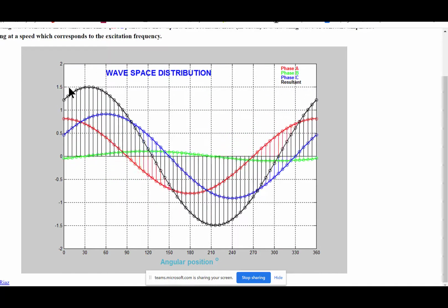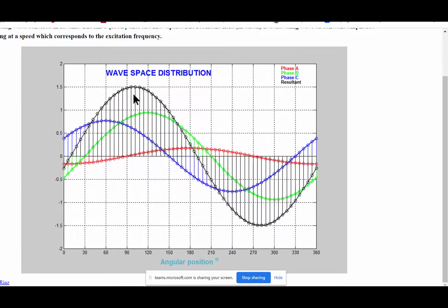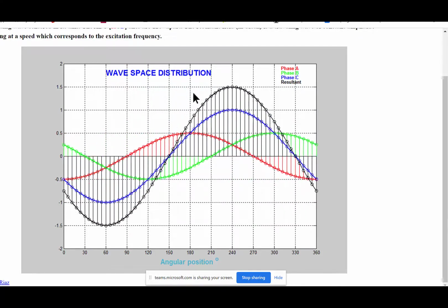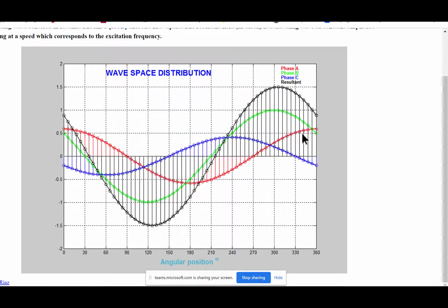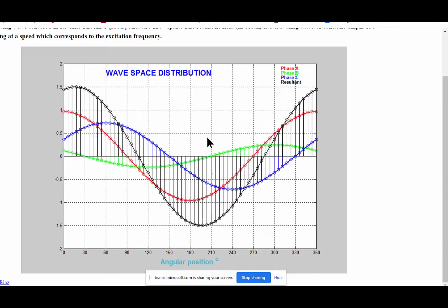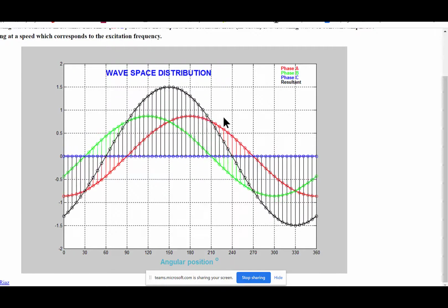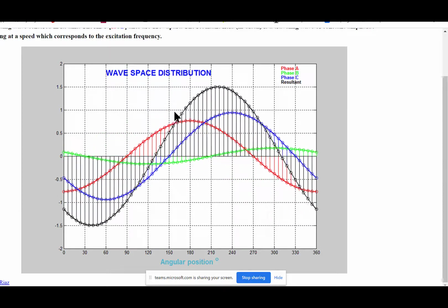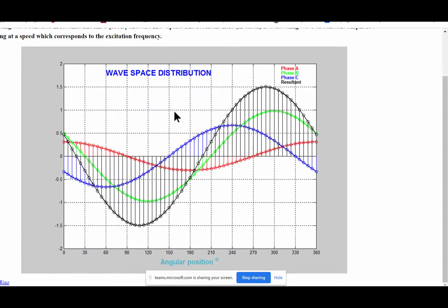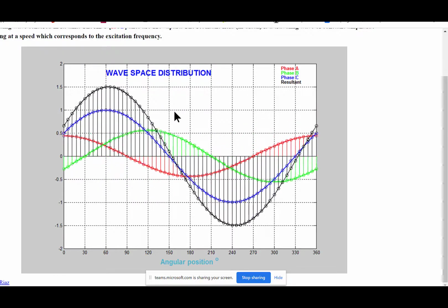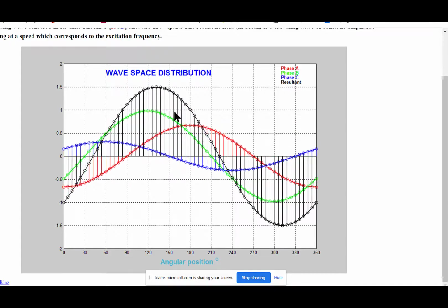If you instantaneously add up all of those currents, you can see this black line is like a sine wave moving from left to right. So you have a motion. The MMF, this was on the synchronous machines, so the stator winding is the same for the induction motor and produces this MMF that's moving in a direction.